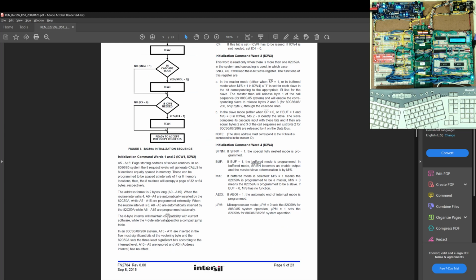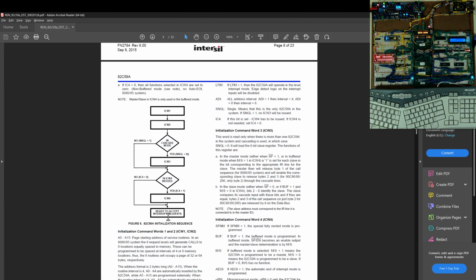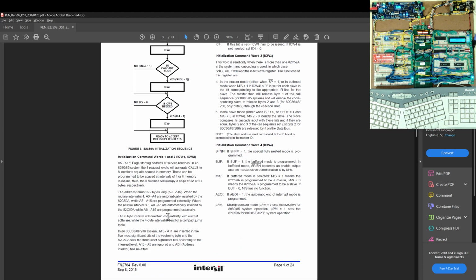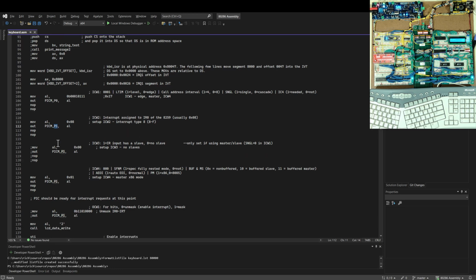And this talks about what address basically is this first interrupt request going to be set to. And in my case, from the reading and the examples I was looking at, it seems like that is always set to 8 for my type of setup. So I am using 0x08 for this. And so that is setting the value, and then I'm going to go ahead and write that now to that other port. Like I said, sometimes called the data port, but P1 in my case.